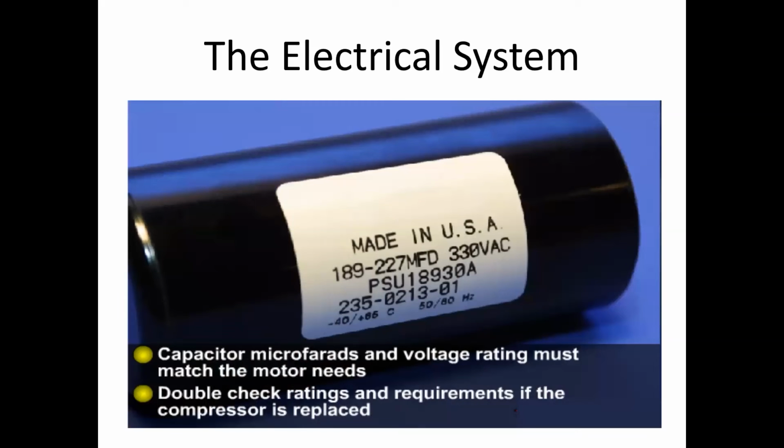And when you do replace that capacitor, you want to make sure that it is rated properly for that unit. There's a lot of times when you go out and you see that a unit has had a dual capacitor replaced, and that capacitor is not the right size for both of those components. It just happened to be whatever that person had in their truck. So you want to make sure that you're using the correct microfarad rating on a capacitor. Don't just replace it with what you have in your truck.